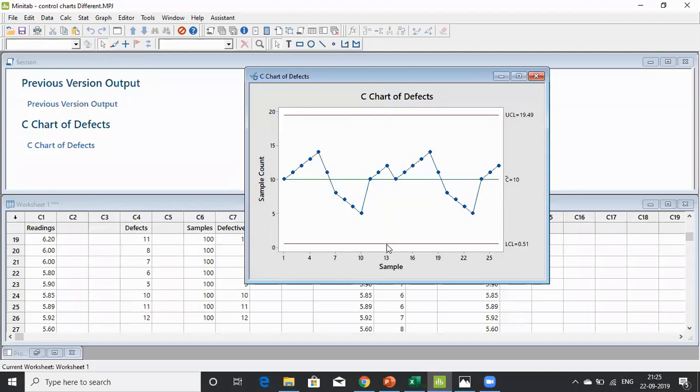So these are the two limits I was talking about. One is UCL and one is LCL, and it is plotting each of those values here. And this is a mid value. It's plotting it here up and down. If any of these values is beyond this, that will be a special variation, which means that process is not in control. Just one point outside it, probably we need to revisit and identify what is causing that. And again, we put some recommendations to it.